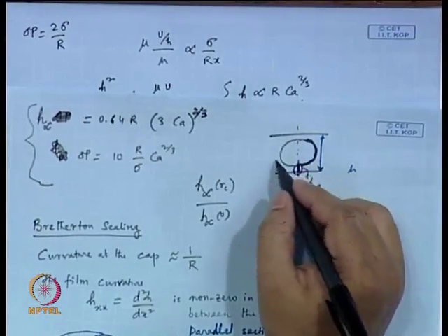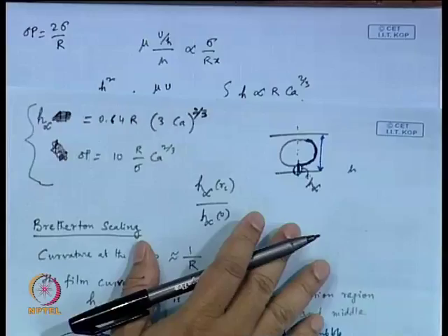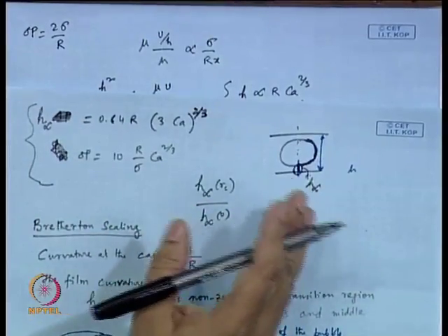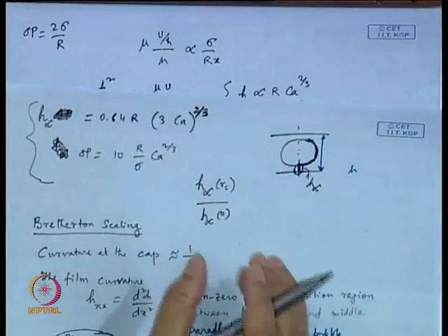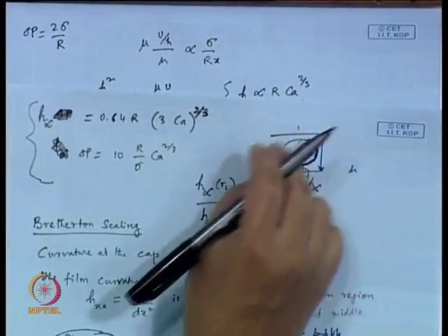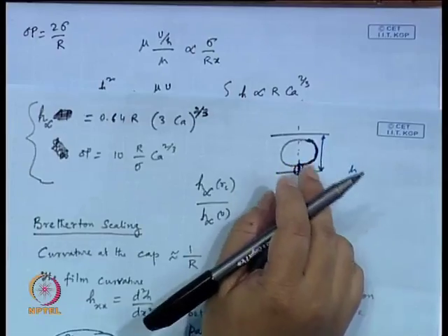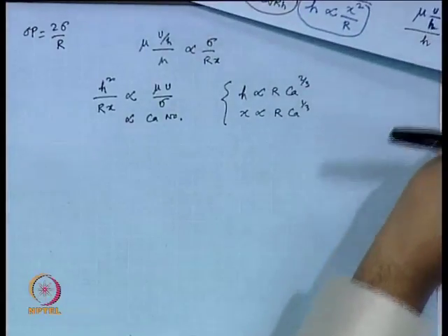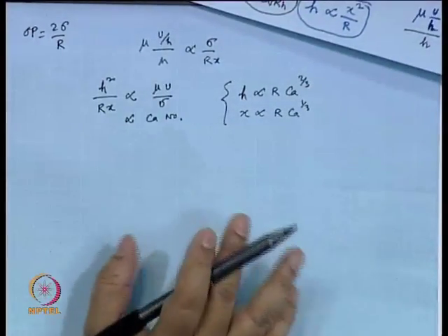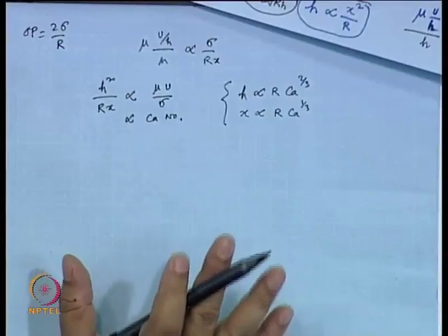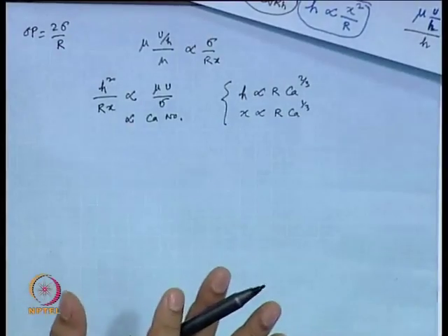So, you are using immiscible phases in the microchannel, but it would be split: there would be an annular portion for the liquid part, and then you will have the other part, droplet or the bubble, at an axisymmetric location. But what are their dimensions? Without getting into a rigorous calculation, you can get some idea of these dimensions simply from scaling. Of course, this is a scaling analysis.